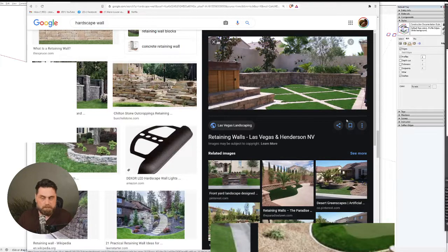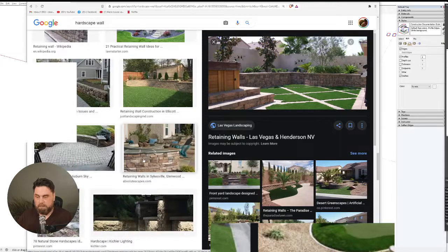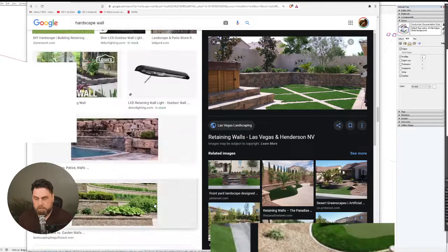These things, like these inlays, if it's not square, then it's a specific angle from square. So we're always thinking in that term. That's why we pull out string lines. That's why we do so many layout markings when we're actually doing construction.